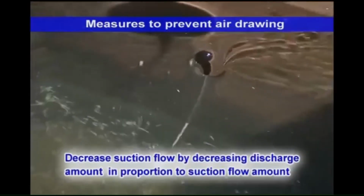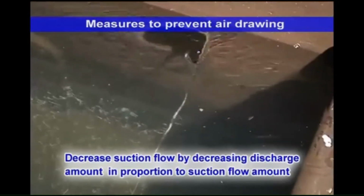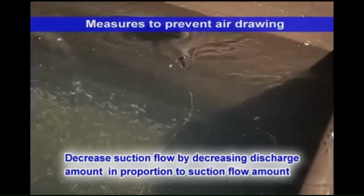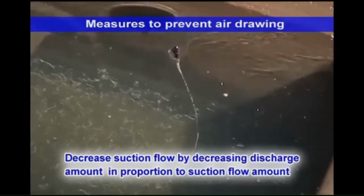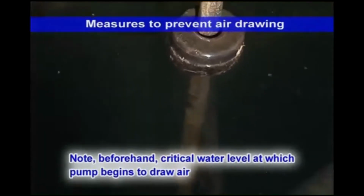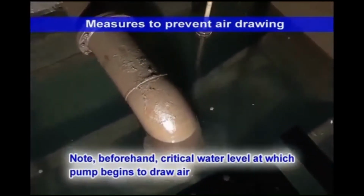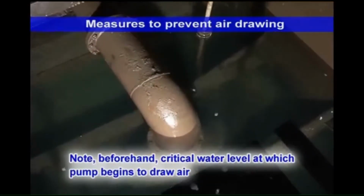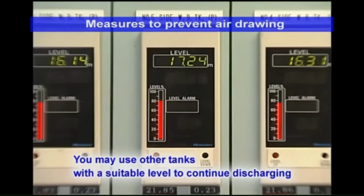To deal with air drawing due to a suction vortex at the bell mouth, decrease the suction flow from the bell mouth by reducing the discharge valve opening to decrease the discharge amount. Note beforehand the water level at which the pump begins to draw air, and stand on the alert as the water approaches the critical level. You may use other tanks with a suitable water level to continue discharging.